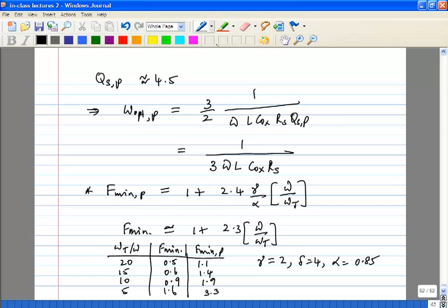Yes, so let's say you take a given size and you burn, let's say, 1 milliamp of current in a 10 micron by 0.13 device. It has a certain Gm, a certain CGS, and a certain omega t. Double the current to 2 milliamps, what happens? Gm goes up, whereas CGS stays the same. So omega t will automatically get better. So when they talk about omega t for a particular process, what they are talking about is for a given size and given current consumption and so on.